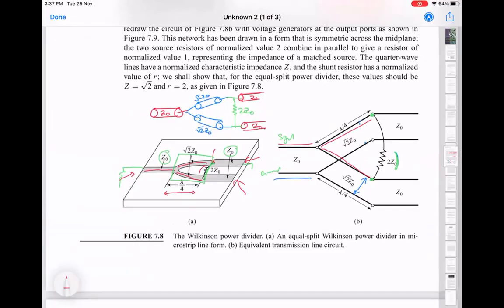Let's get started. So we'll finish up what we were discussing last week, which was this Wilkinson power divider, which had most of the ideal properties we wanted from this 3-port power divider. That it should be matched, it should have isolation, and also that it is lossless. And in this case, as we discussed, it's lossless in a special way, but in the most commonly used case, which is basically when you're sending input from one end and you're taking equal powers out.